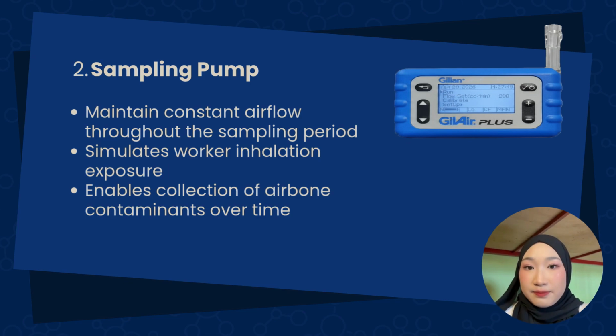Second is the sampling pump. The sampling pump is used to maintain constant airflow throughout the sampling period. It also simulates worker inhalation exposure and enables collection of airborne contaminants over time.